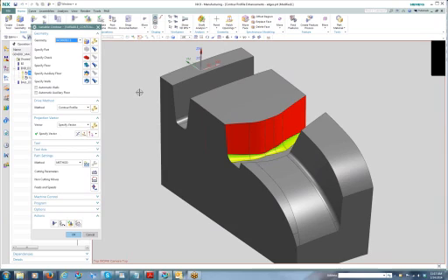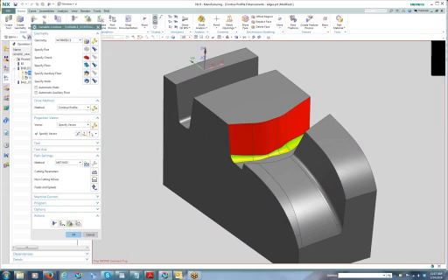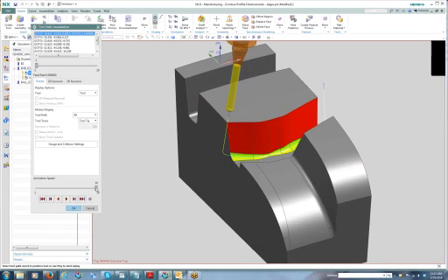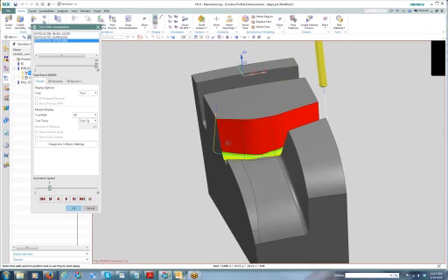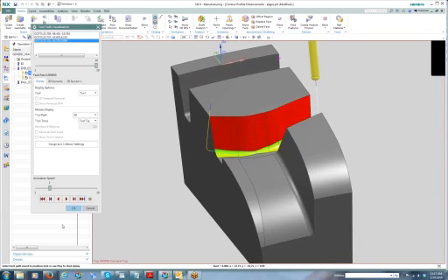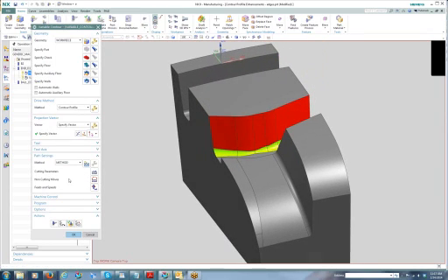Here's another example of swarf drive type machining using our variable contour operation. If we look carefully at it as we just run the cutter down this existing pass, you'll see that the tool axis is changing pretty aggressively from one end to the other. This is our default for our tool axis.